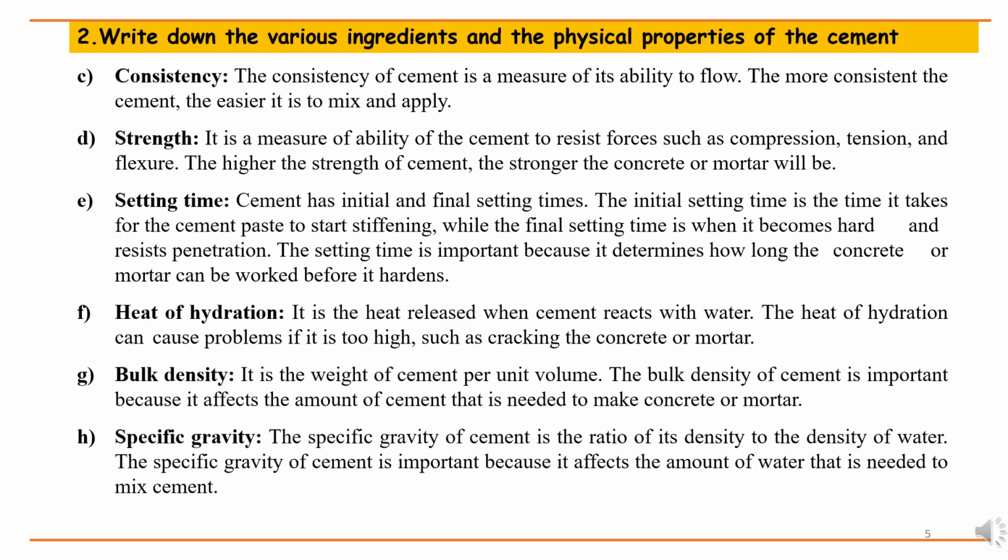D. Setting time. Cement has initial and final setting times. The initial setting time is the time it takes for the cement paste to start stiffening, while the final setting time is when it becomes hard and resists penetration. The setting time is important because it determines how long the concrete or mortar can be worked before it hardens.